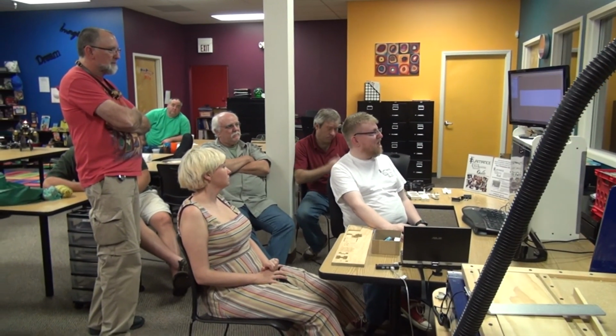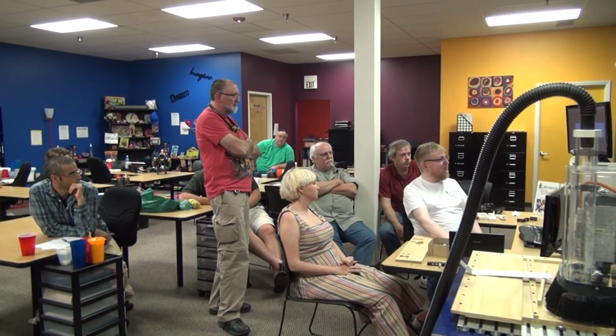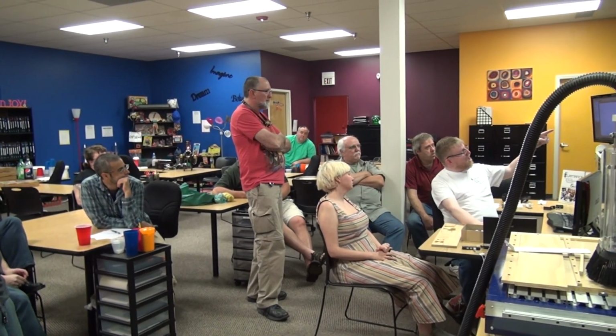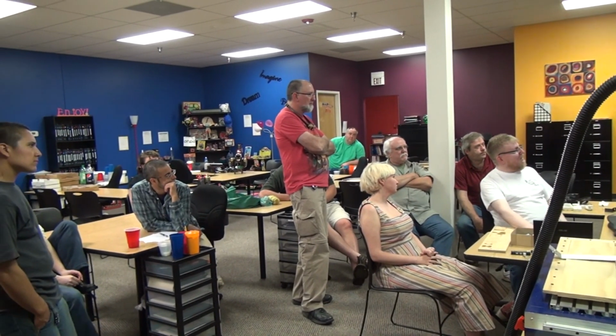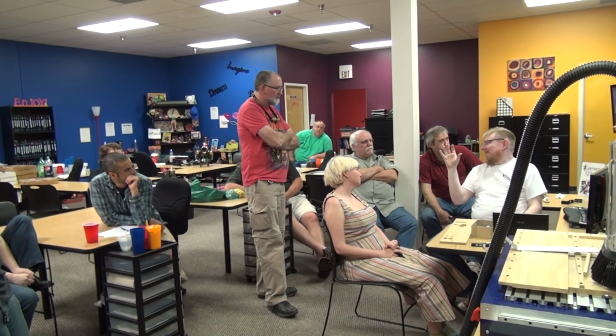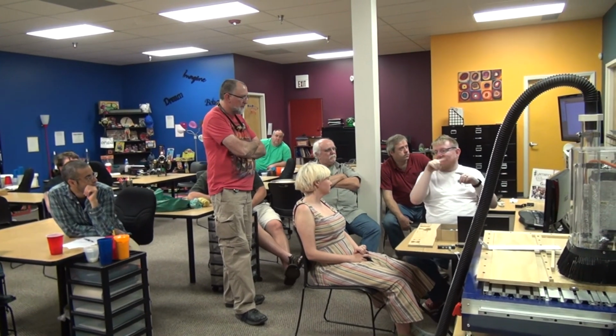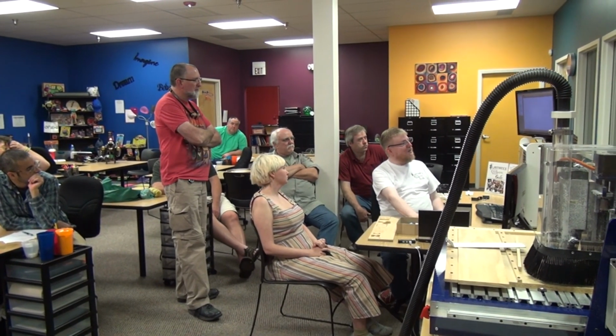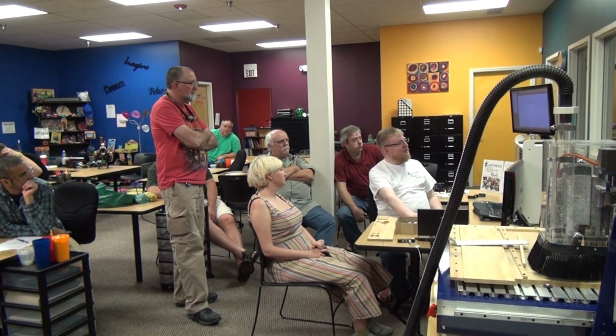I'll show you the fillets. So I'm going to make myself another rectangle, and this time I'm going to make some fillets on it. So here's my choice: normal, dog bone, T-bone. I'm going to make a dog bone fillet, and you can set the radius. You can do anything from the tool diameter up. So I've got an 1/8 of an inch bit, so I could have an 1/8 of an inch. I don't really need that because I would do that anyway. I'm just going to leave it at 1/2 to be exaggerated. You just click on the corner and it'll make those dog bones for you.